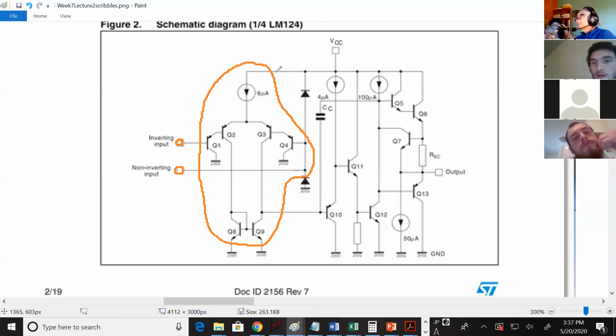Okay. Same thing as the last circuit, the last amplifier we looked at. They're using PNP based, in other words, PNP input transistors. What do you notice about the input transistors? There's a PNP going into the base of a PNP. Is it for level shifting?